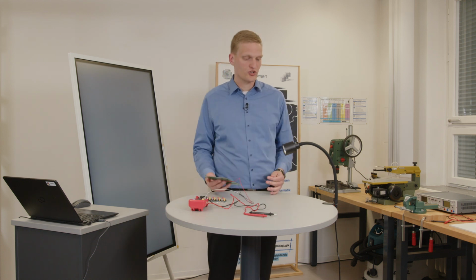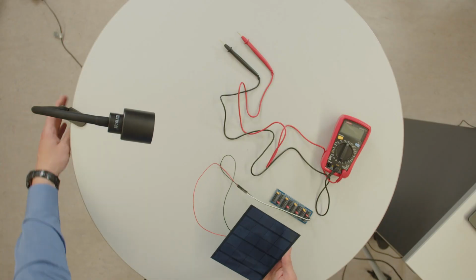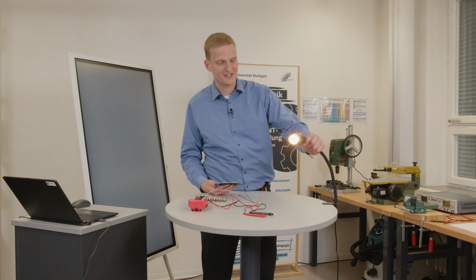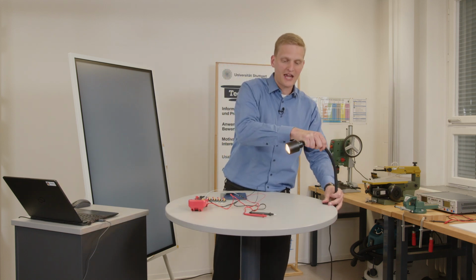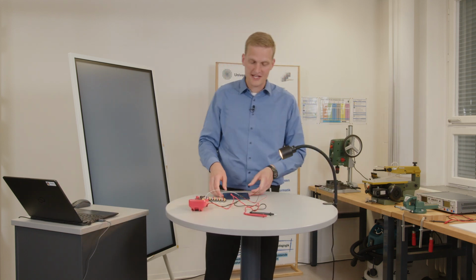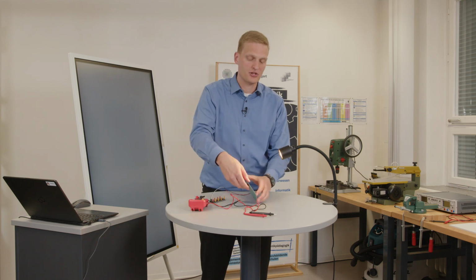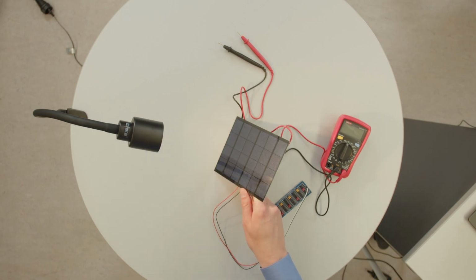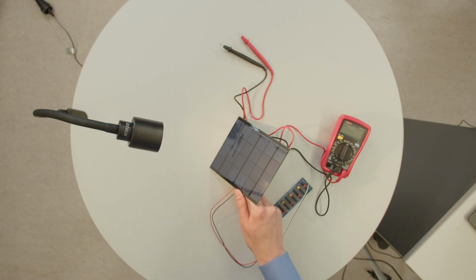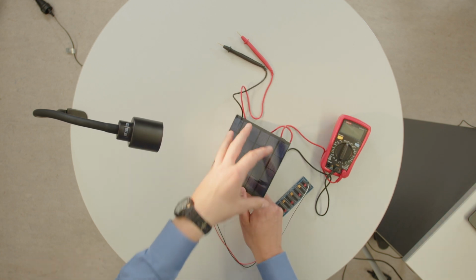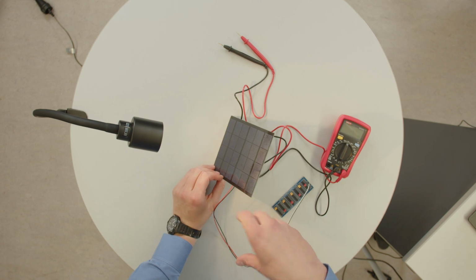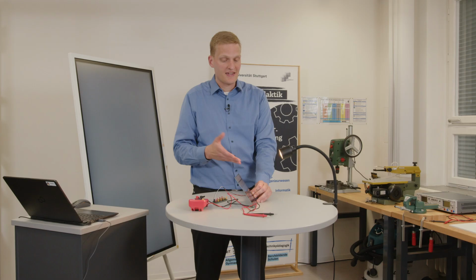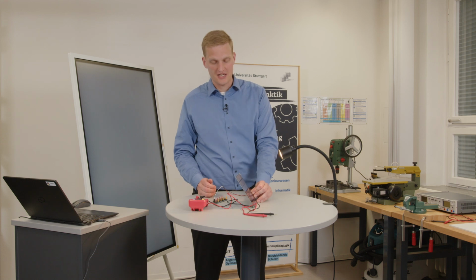We need a controlled condition. Therefore, we do have this artificial sun here. Now it's shining, you can see it. It gives us always the same light when we do our measurement, because if we do it outside or just by daylight, a cloud might come before the sun, the light changes, and so does the solar panel, and the maximum power point also changes, and that is what you can figure out with this experiment.